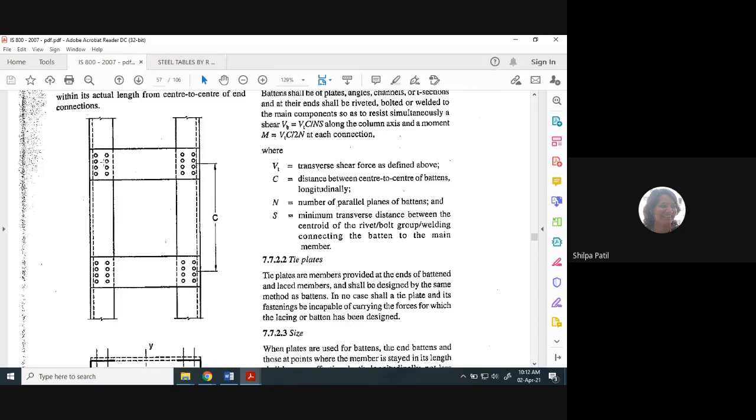Okay, and when these horizontal plates are subjected to this vertical loading which is acting on the column, the plate is subjected to bending moment and shear force. So these plates are designed like a beam. See, you can now just imagine how it is difficult to design, not difficult, but it is a tedious task to design built up columns. You have to design the column first, and then you need to design this connection system also.